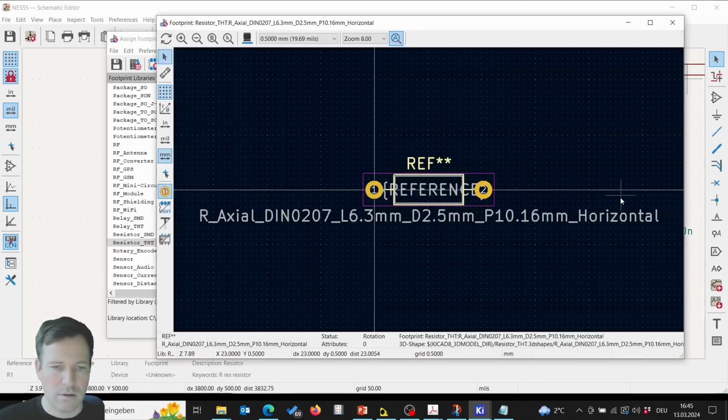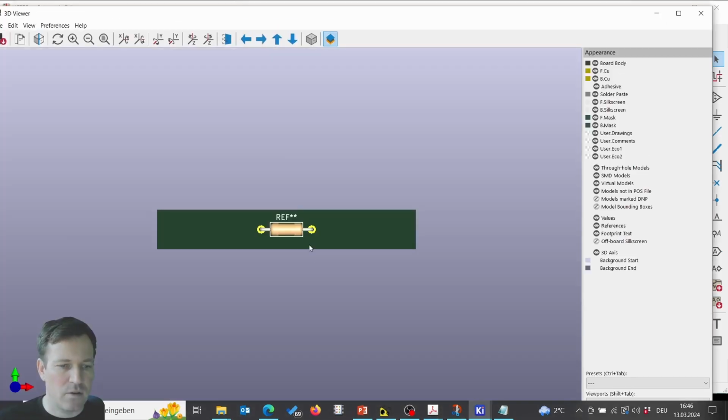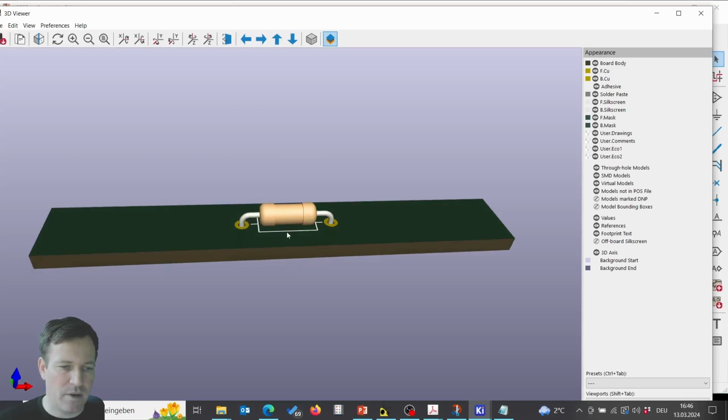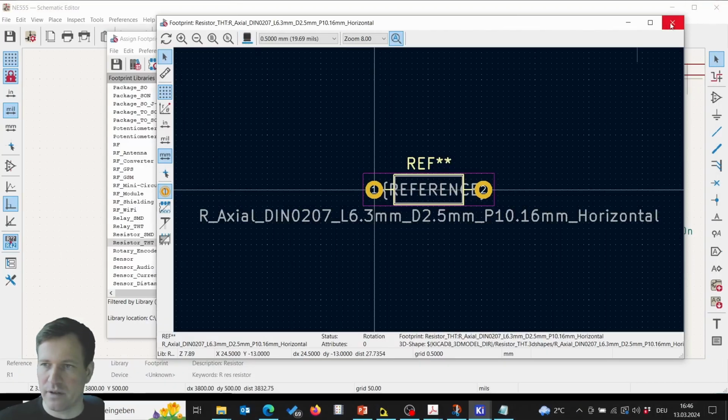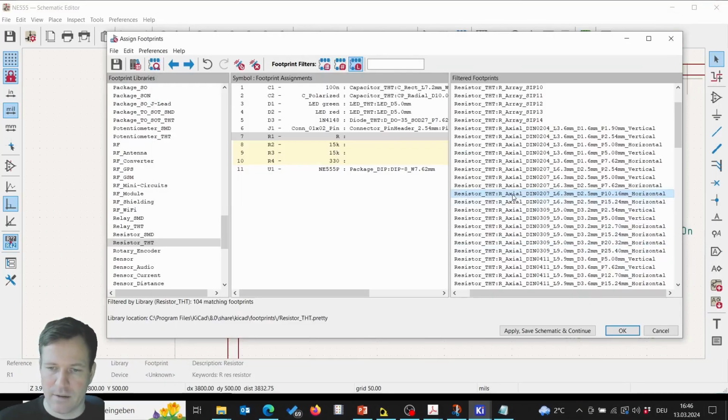Let's have a look. Yeah, you see here, now the bending is not so tight at the package. We assume, yeah, and this is seen here. There's a little bit more distance, make it easier to assemble later on and doesn't stress so much the components. So we take this footprint, for instance, in this case.